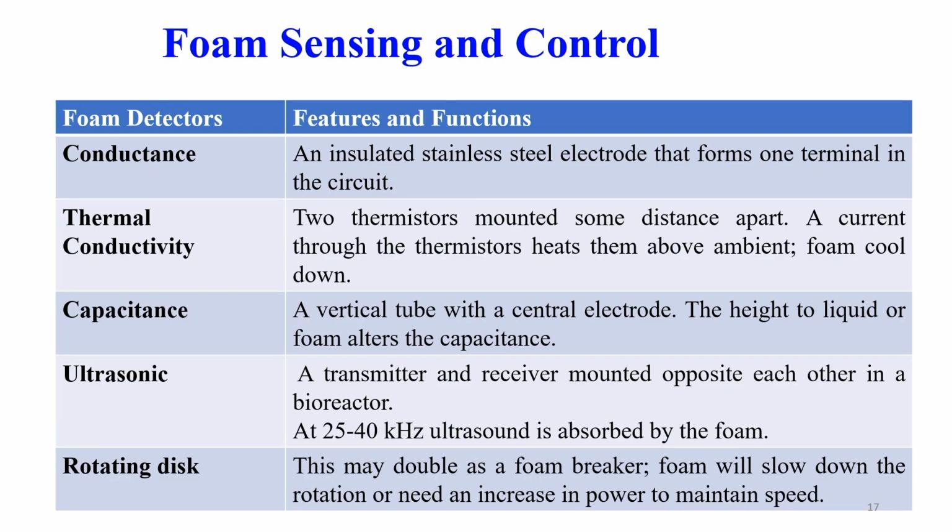Next comes foam sensing and control. There are different ways to sense foam. One is the change in conductance. If you have an insulated stainless steel electrode, once it touches the foam there will be a change in the conductance.